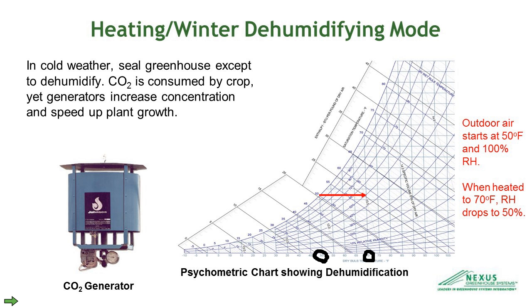That's correct. And so a lot of people will tell you at this point, well, I'm worried about my CO2 concentrations going down inside my greenhouse because I'm exhausting air in the spring or in the winter months when I'm supposed to be sealed up. And sure, that is a possibility, but we have a solution for that. What we do is we add CO2 generators inside the greenhouse, which is designed to allow for 1 air exchange an hour and maintain a high level of CO2 inside the greenhouse. You can also use CO2 generators first thing in the morning before it heats up outside in a warmer climate and add CO2 to your grow room that way.